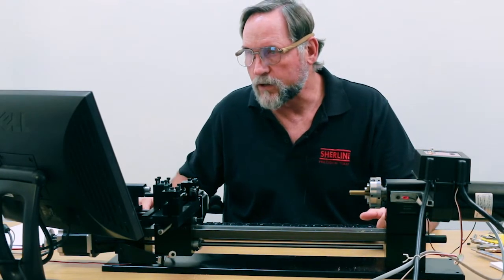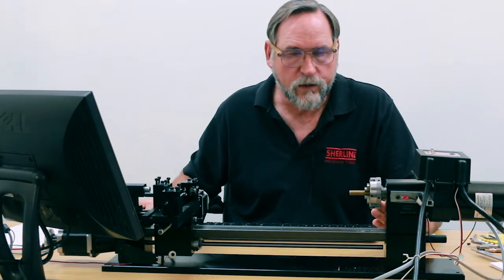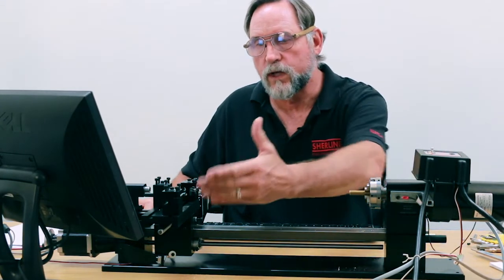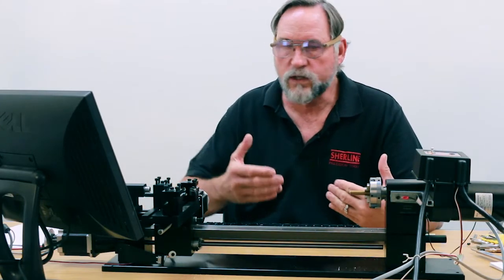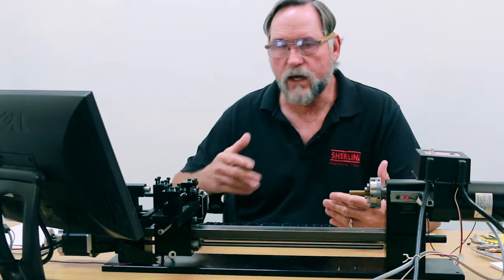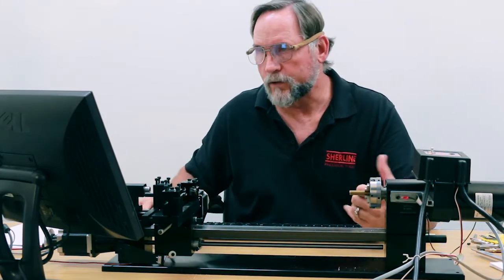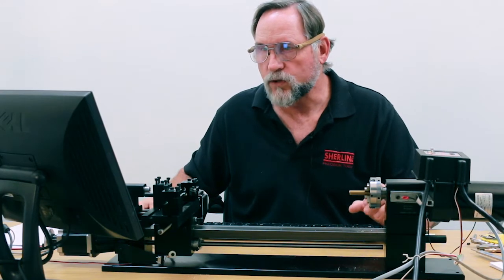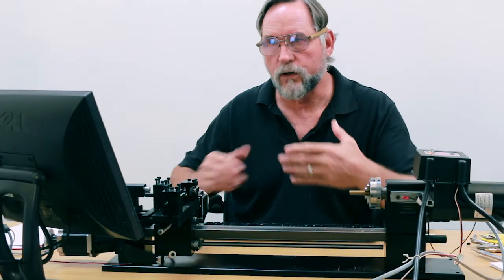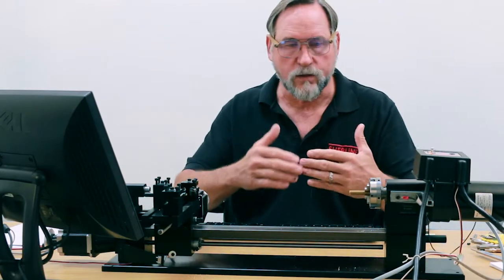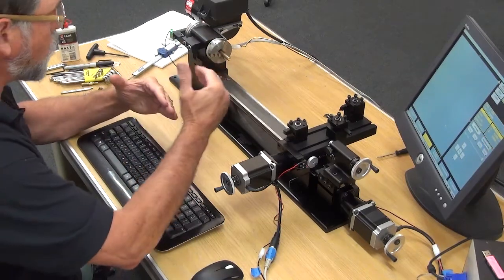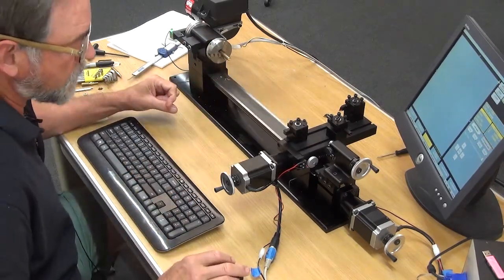To do this, I always write my program in short programs for each tool operation. Once I've adjusted my feeds and speeds to optimize them, I can put all those programs together. Short programs are also a lot easier to edit. I don't have to go through 500 lines to get down to where it's doing this one operation. I'm just dealing with what that individual tool is doing.